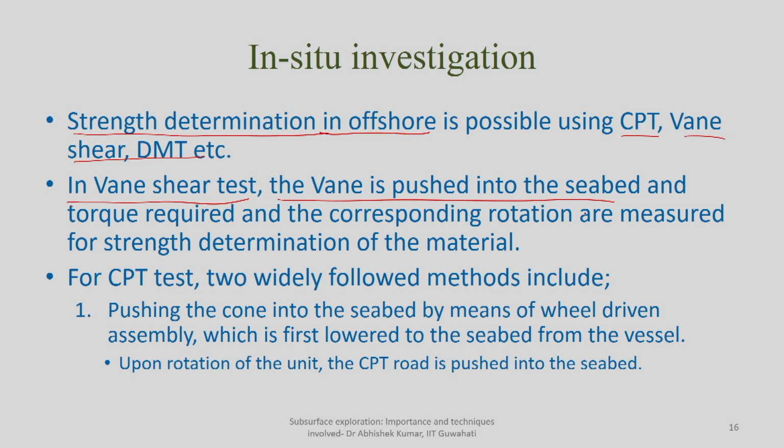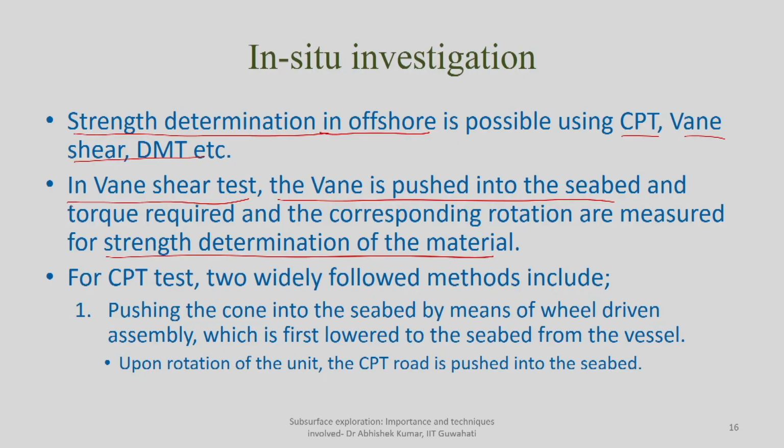So, the vane is pushed into the seabed, and the torque which is required and the corresponding rotation are recorded. As we discussed in case of onshore also, what is the rate at which the rotation has to be done, and the torque which is required to ensure that particular rate of rotation is recorded. And these two things will help you in understanding the shear strength characteristic of the material, because the sample in which you are actually inducing torque is undergoing shear failure. So, that is how you can determine the in situ shear strength characteristics using vane shear test, even for offshore